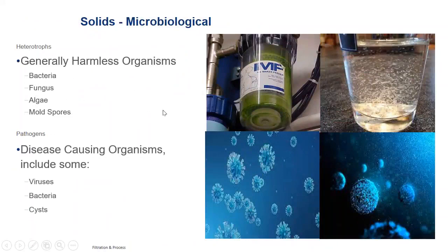One of the most common harmless ones that we see that's a real nuisance in water treatment is the stuff called water mold or slime molds. This is actually a bacteria that produces a mucus coat. And this mucus coat demands a high level of sanitizer to break down.